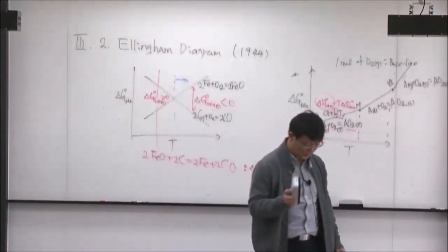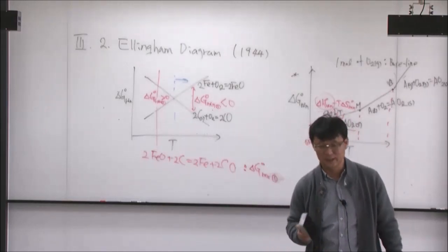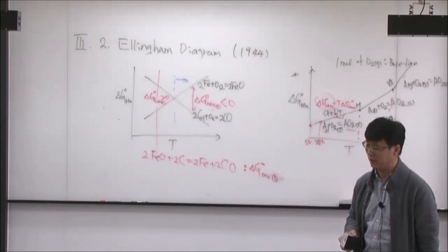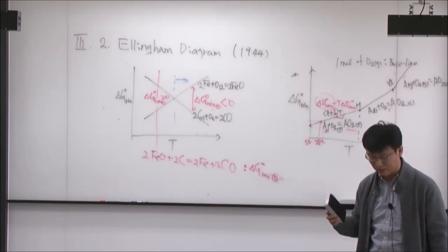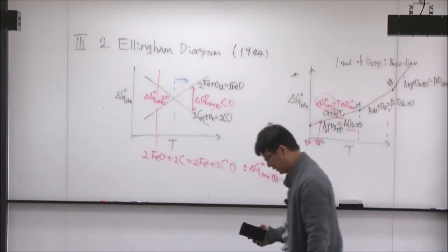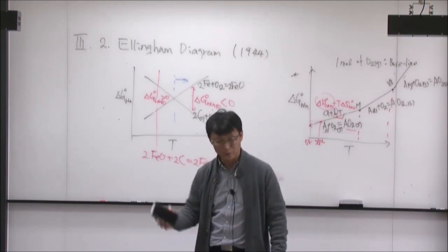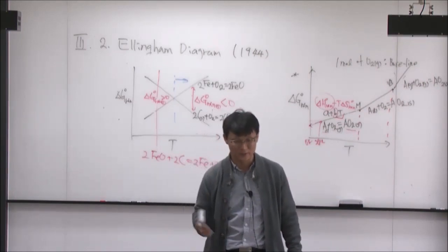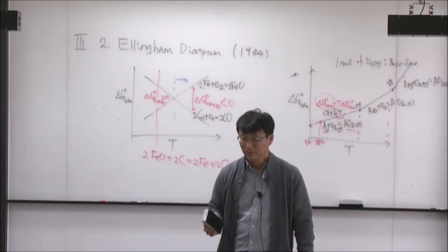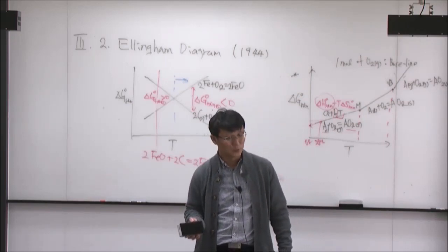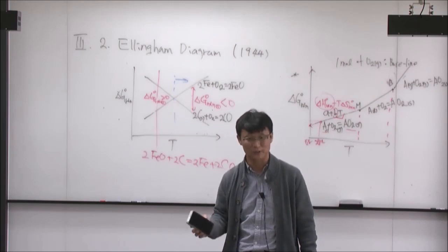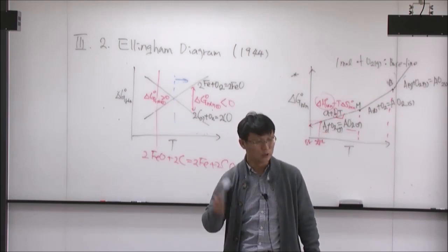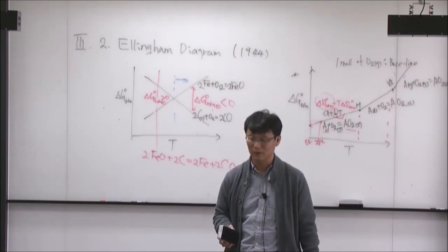But one of the very interesting additions inside of the Ellingham diagram is, okay, from the diagram we can now understand what is the equilibrium partial pressure of oxygen to control, to make a reduction and the oxidation happen, okay? But in most industrial processes, we control the partial pressure of oxygen by using a CO-CO2 mixture or an H2-H2O mixture, okay?